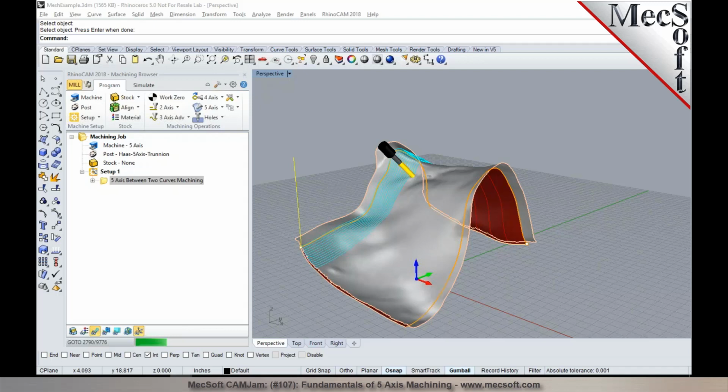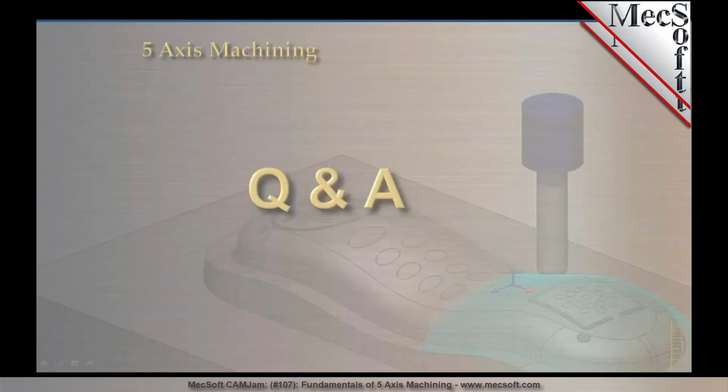One is you should understand that for every orientation, there's actually 2 solutions that we can come up with for the rotary axes. So the first time around, we will look at the nominal or the closest solution to the previous point. And if that is outside of the machine tool limits, we check the secondary solution and see if the secondary solution actually does satisfy the extents or the machine tool limits. And if it does, we will use that.